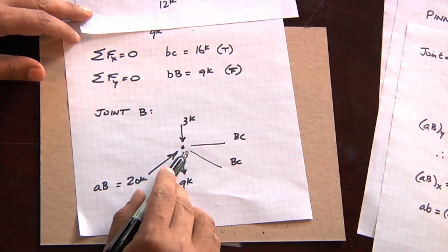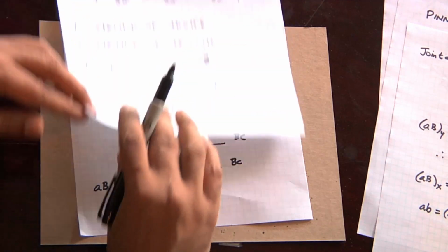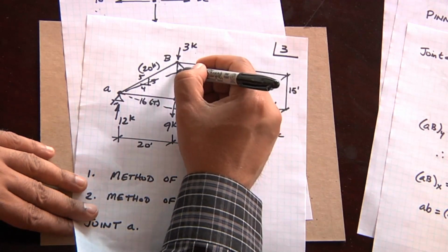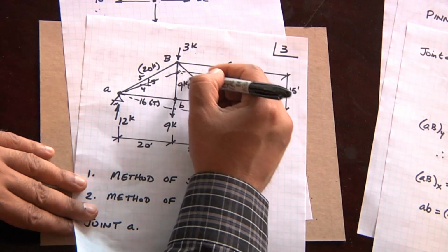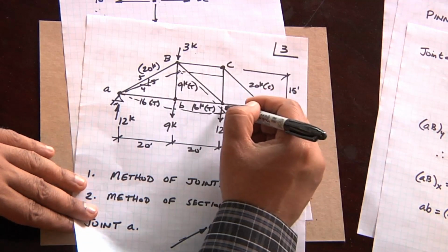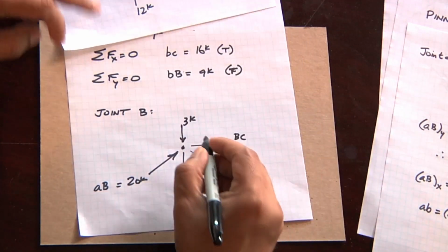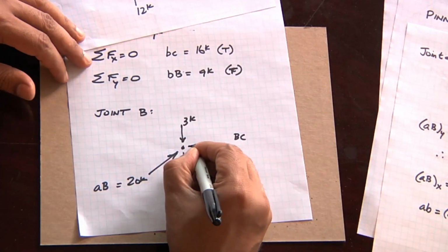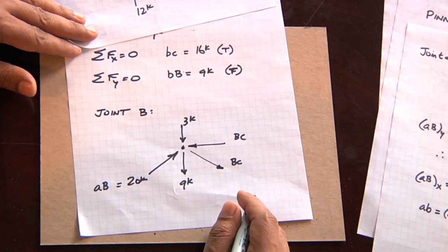In this case, the chord running diagonally here, from looking at the deflected shape, will be extending. That diagonal chord is going to be in tension. The top chord is going to be in compression, and I'll prove that to you in a moment. But if we draw it in there for now, that's going to be the final load diagram.